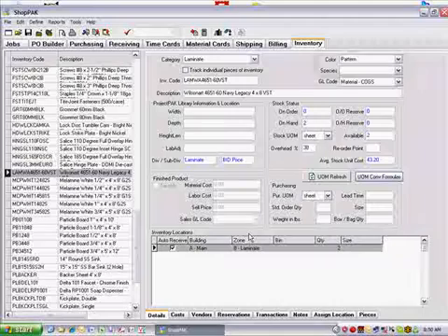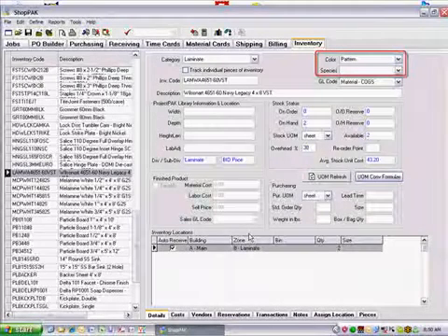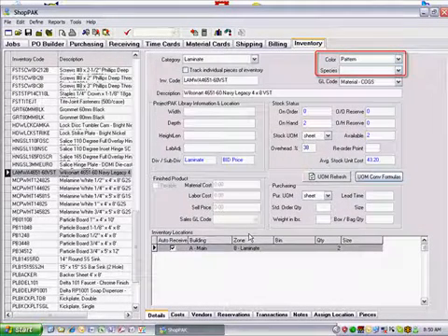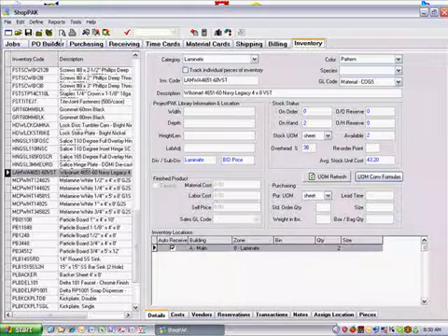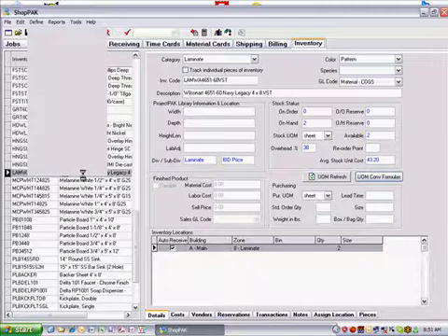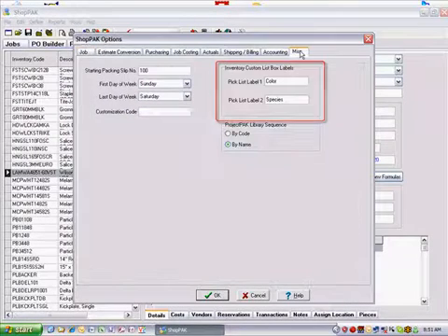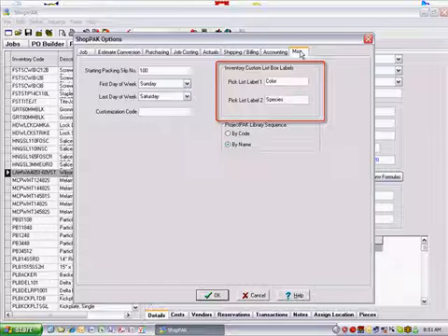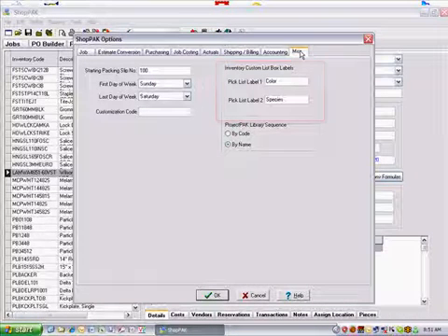The inventory form has 2 optional user-defined pick boxes. The values you define are available for all inventory items. To set up these pick box values, go to the Define menu, select ShopPAK Options, and then select the Miscellaneous tab. As you can see, we've defined color and species for our user-defined pick lists.